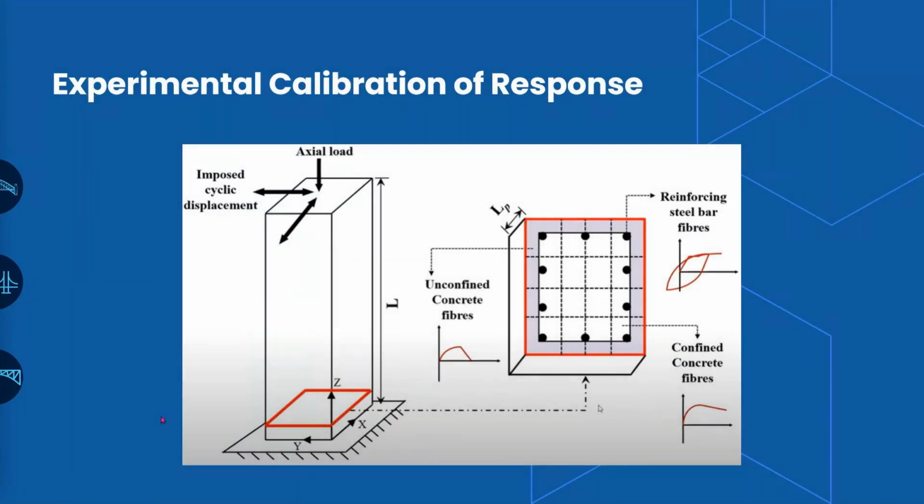So once we are done with the selection of the time history records, it comes down to the modeling of our structure for the nonlinear behavior. You can identify this figure that we had discussed before. This is basically a fiber model of one of the plastic hinges that we can consider. It is very important to consider a correct hysteretic model or a correct nonlinear model for that particular structure so that the assessment is accurate. And hence, generally, the calibration of these types of hysteretic models is required before assessing a particular structure.